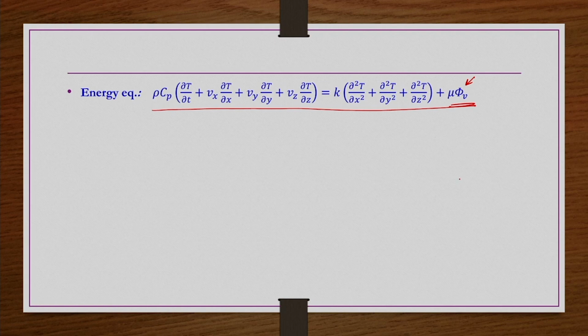So, in general when you write the energy equation, we take only the temporal term, the convection term and the conduction terms. Other terms, as per the requirement of the problem, reaction terms, viscous dissipation, etc., whatever are there, if specific to the problem, then only we write, otherwise we do not write. So, now specific to this problem, the viscous dissipation term should be included. So, that term is this one. We expand this one in the next step. Before that, we simplify this equation. Steady state, so this term is 0, Vx is 0, Vy is 0, Vz is not 0, it is there.